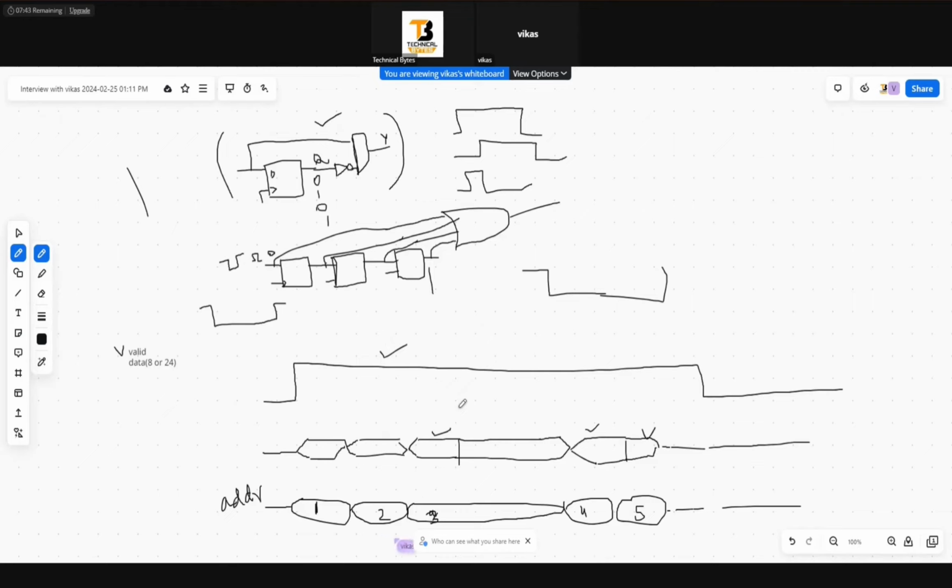Yes, sir. So what I'm saying is, let's say we are putting everything inside a FIFO, maybe. For the FIFO write enable, the condition will be this valid and input address not equal to the registered address. Very good. Can you draw that particular logic?